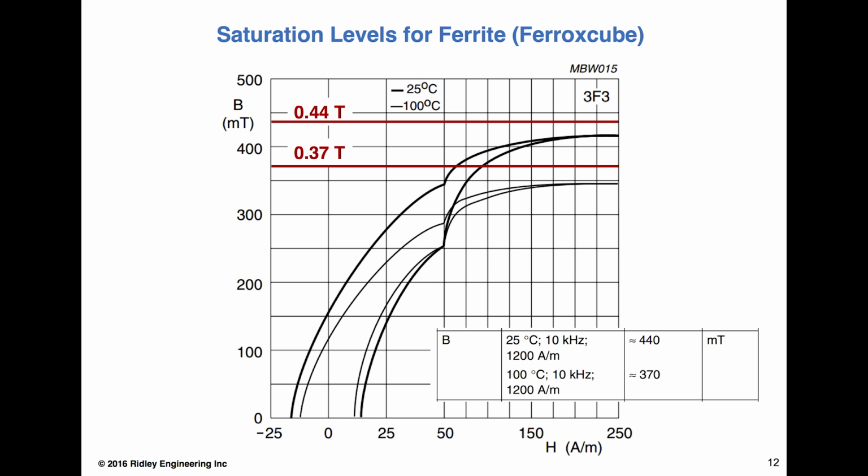But one thing I have seen in the past, which you're probably alluding to, is, I bought core materials from TDK, Ferroxcube, Mag Inc., etc., and then the customer maybe has gone to a second or third tier supplier that claims to have the same material, and then you put it in your circuit and it's running a lot hotter. And there are no controls on this, there's no standards on this that are in place right now. It's certainly something that's needed in the future.